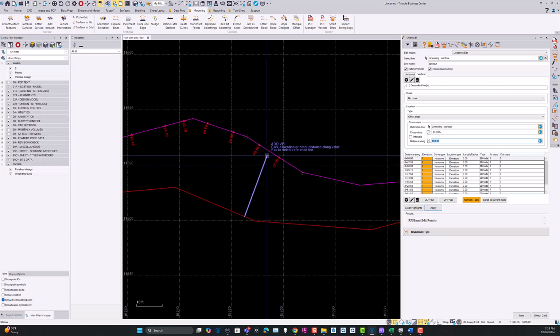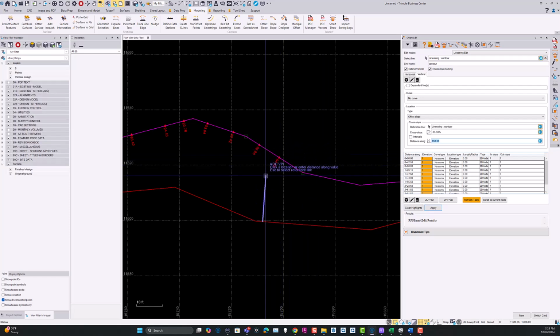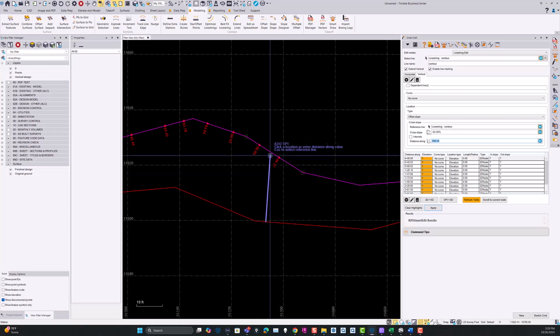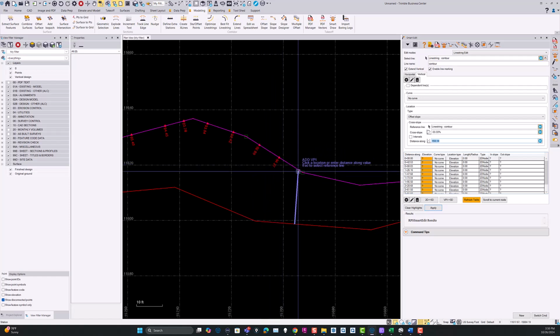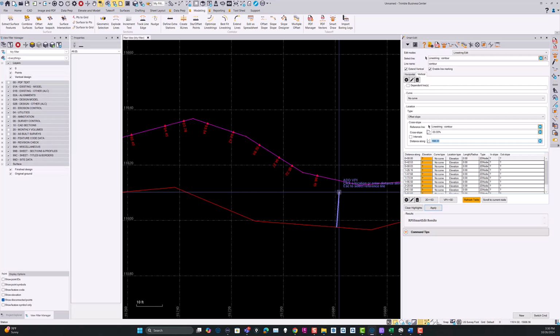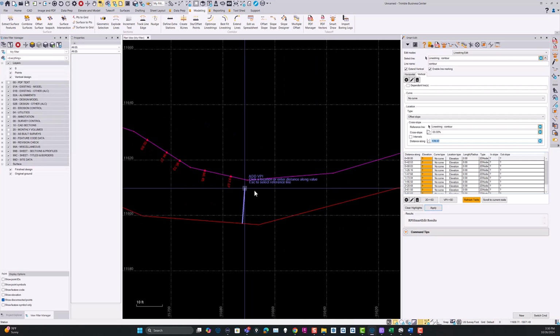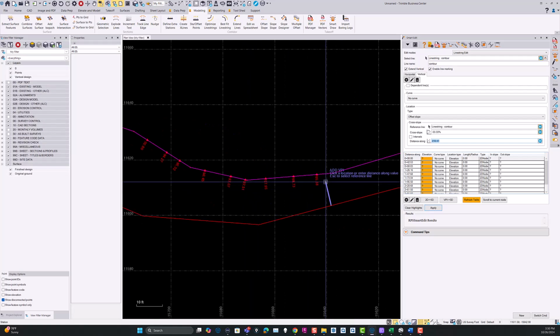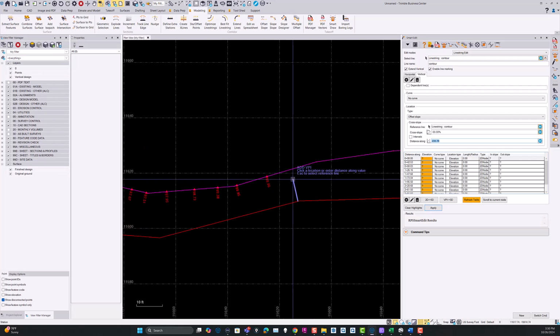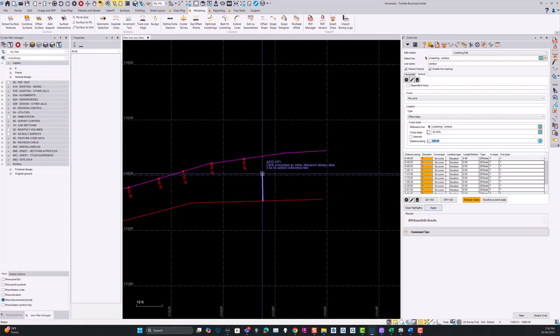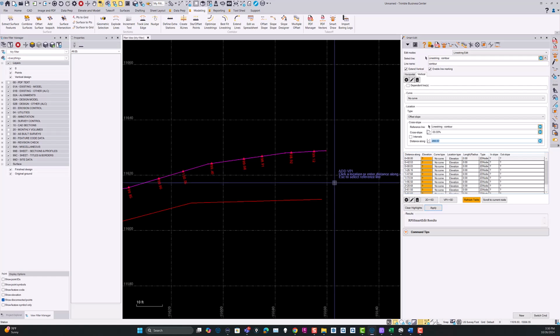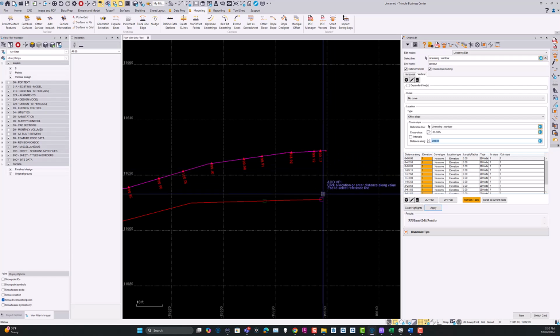And this stops it from giving you the overlap zone, because of course if you project a line from here perpendicular to the reference line and you do one from here, you're going to get a crossover zone in here to calculate. And so by doing this we can set the elevations wherever we think we need to, just at random intervals along the line. I'm just going to do a few more here just to kind of set this, and at the end here we can just pick the end point and it will calculate that.